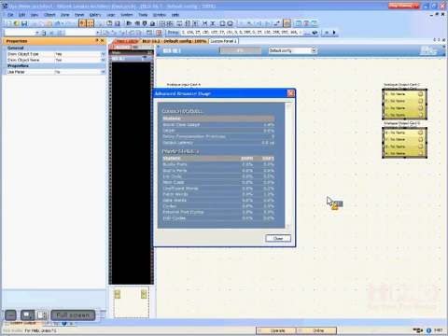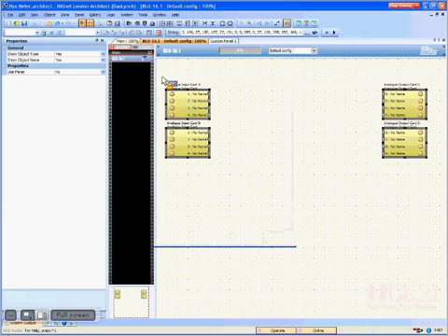Nobody has a guess? That last 1.4% is the 1.4% you cannot turn off in a Blue 16. It is, again, meters. Those flashy little front panel lights, little meters on the front of the Blue 16, have to be controlled by a DSP chip. They're controlled by the Shark chip. That's 1.4% of its processing power used up by those front panel meters. No way to turn them off. So that's the best you're ever going to get.